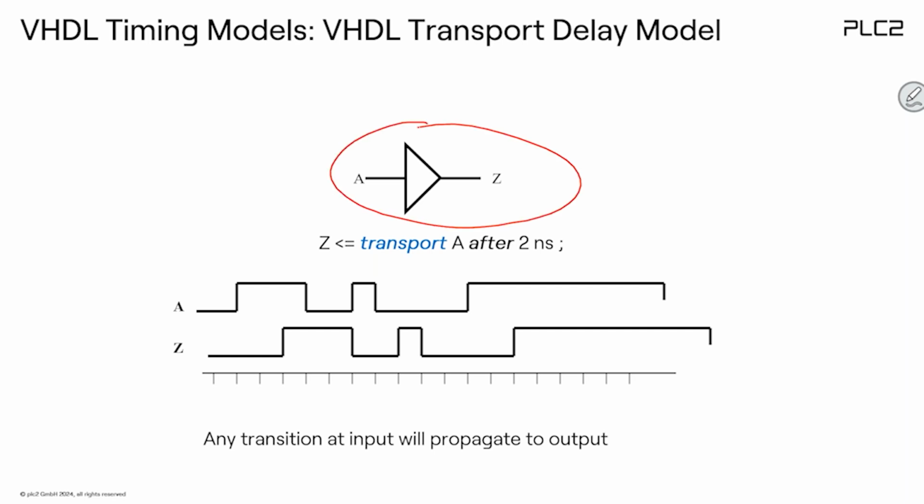So in this case, what happens is that all of the signals which are arriving at the input will appear after a certain delay on the output, but the signals are not suppressed or rejected. So this is basically the model of a cable, maybe a coax cable or just a delay line, because it's also part of your test bench, maybe.